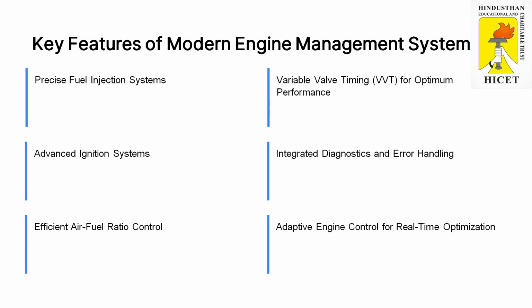The next is variable valve timing for optimum performance. If you are making advancements in engine operations, the VVT or VTVT varies the valve timing, with either advanced opening of valves or retard opening of valves. Based on that, the air fuel entry and combustion all advance or retard.